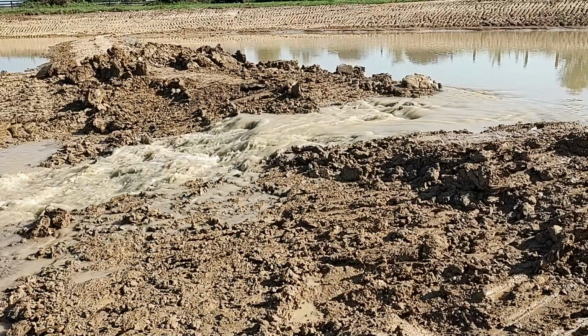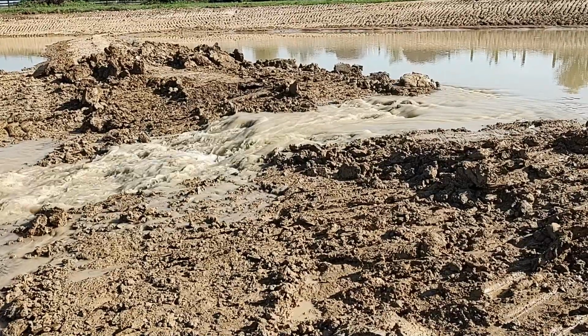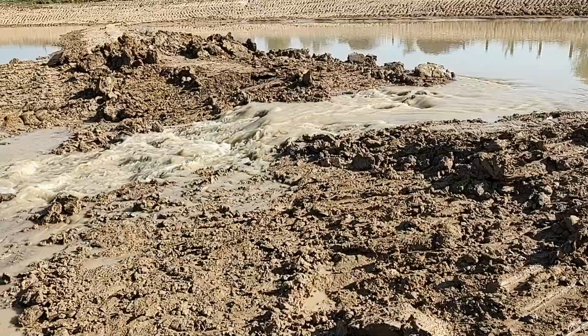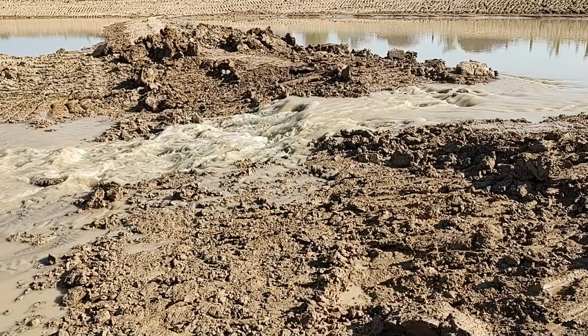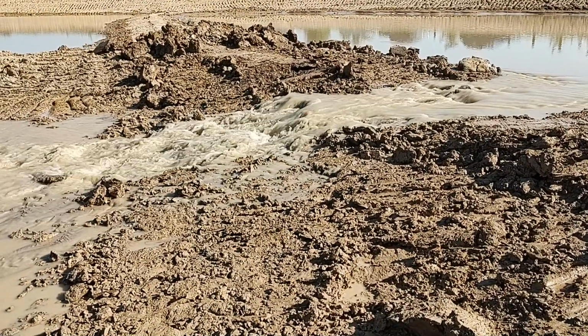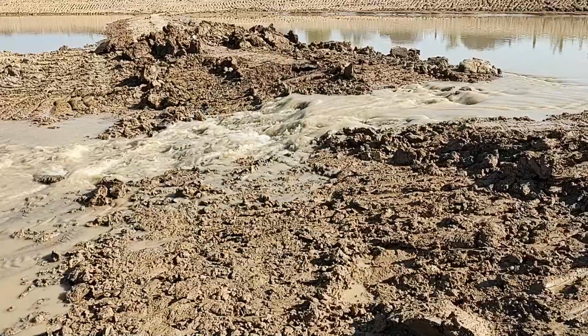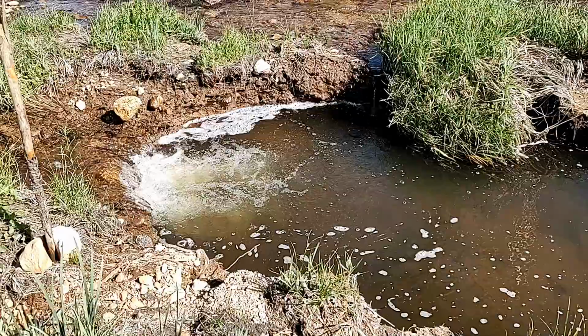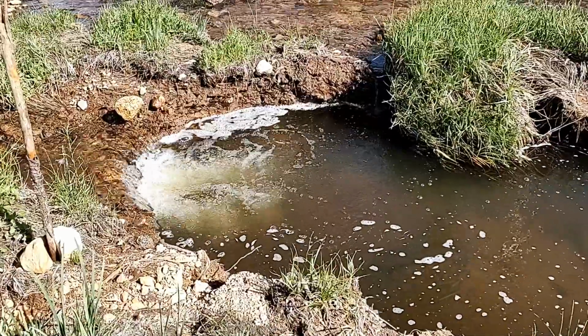You're watching water flowing in a temporary ditch we dug to drain water for the construction of a wetland. Riffles can be seen where the stream is flowing over rough places in the bottom of the ditch. These rough places, which are also called nick points, are triggering head cuts to form that will be visible once the water in the ditch dries. Head cuts form rapidly and get worse in a hurry.